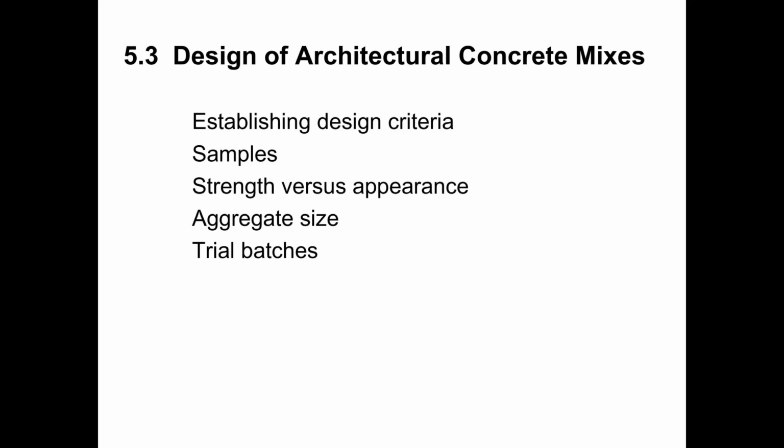That absorption testing needs to be completed before the mix goes into production because there are limitations on how much absorption is acceptable. An architectural face mix should have an absorption of 6% or less. So it's important that we conduct our absorption testing before going into production so that we've confirmed that we're meeting that PCI requirement.